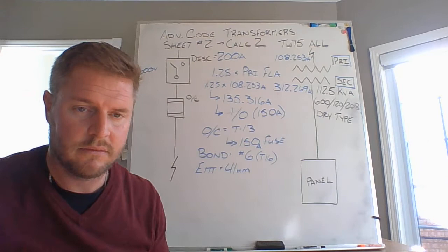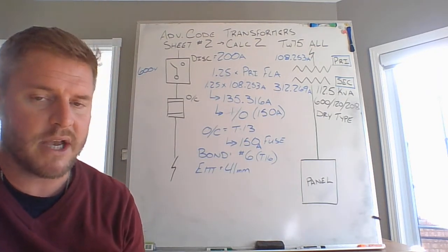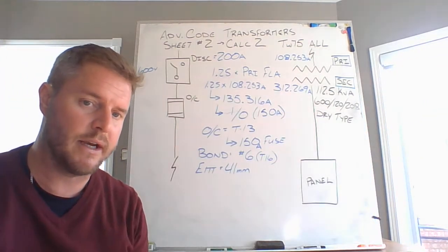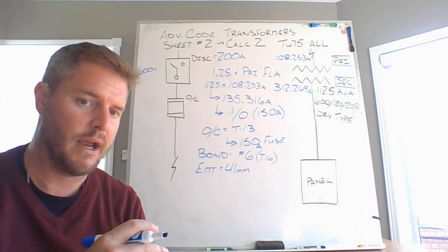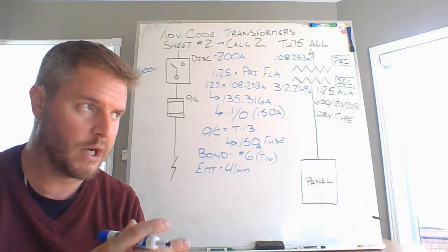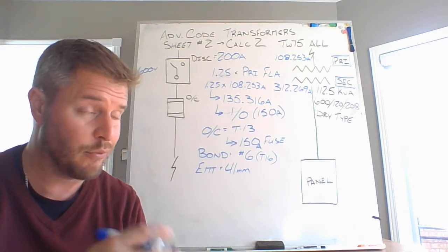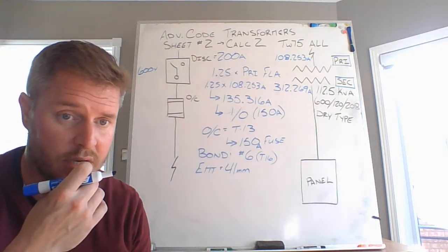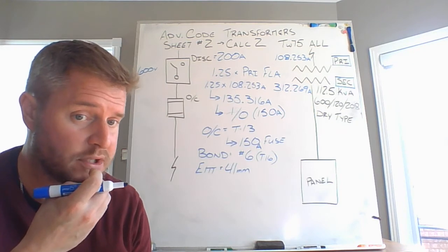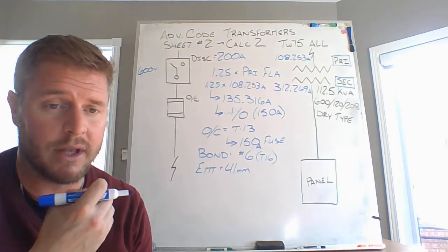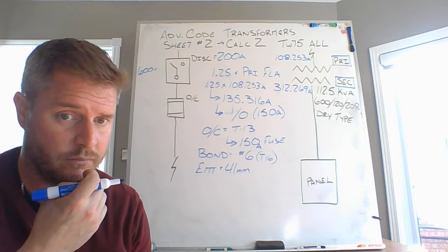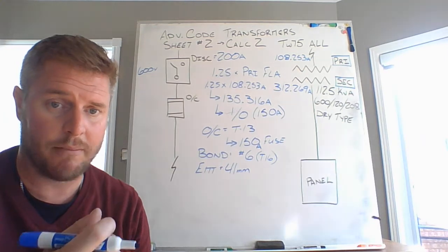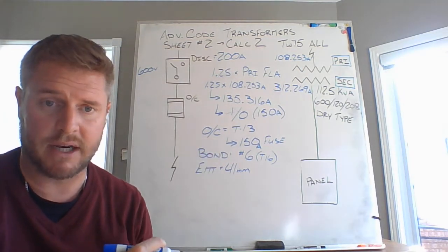Take a second and absorb that information for the primary side of this transformer calculation. And in just a second, I'll come back and I'll do the secondary side when we're looking at the X side of the transformer, X1, X2, X3, line 1, line 2, line 3, red, black, blue, secondary side of the transformer. Because now we're dealing with multiple voltages. And if I have a 120, 208 volt system on the secondary side, I'm more than likely going to be in a Y connection. Okay, so absorb that information for the primary side. In 2 seconds, we'll come back. I'll have a blank screen and we'll do the secondary side.